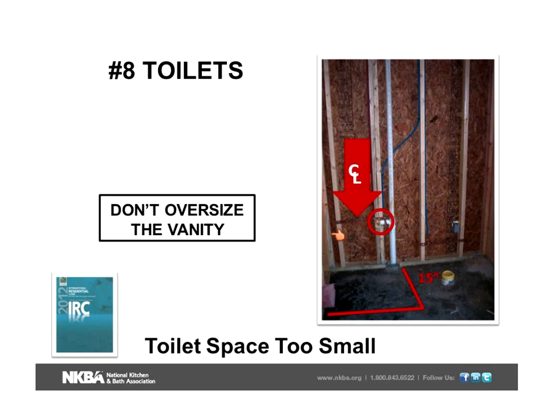What the plumber may have thought is a 3-inch filler and a 24-inch vanity, which puts you 15 inches away from a vertical surface, which you have to have, but I don't have to have 15 inches from the center of a lav to an open area. Again, you want to make sure you have room for the toilet, and then you back up and get your vanity size.